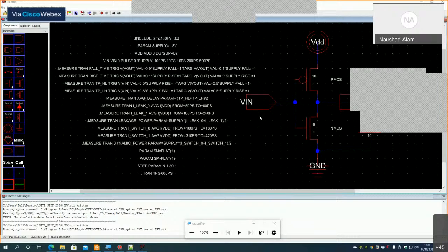I decided to go through the Electric path because in the next session, we will be learning about layouts. And there, schematic and layout must be done in Electric to follow the design flow. If you recall the custom design flow, the design entry is schematic based.